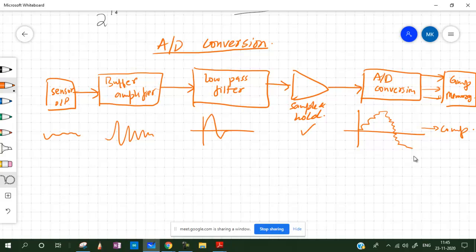That's why we call it buffer amplifier. It amplifies the signal because the sensor output from any sensor that you may have seen, that we generally use, a MEMS based sensor, and all those sensors, they are generally very low voltage signals. They may be even in terms of millivolts or sometimes less than that. So we need to amplify these signals to properly take them for AD conversion and putting them to the computer, because we generally operate at 5 volts digital signals or 3.3 volts. So that's why an amplification is required at the first instance.